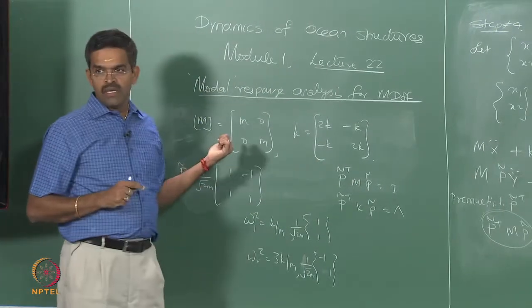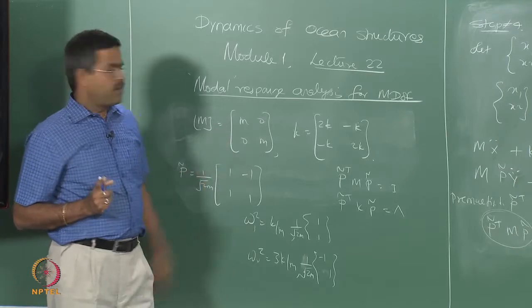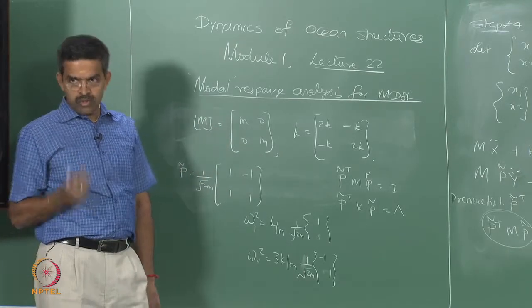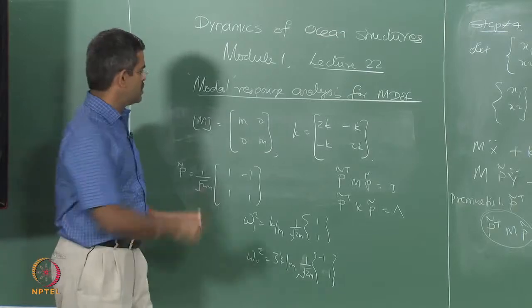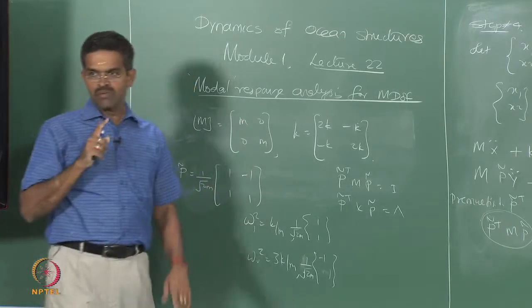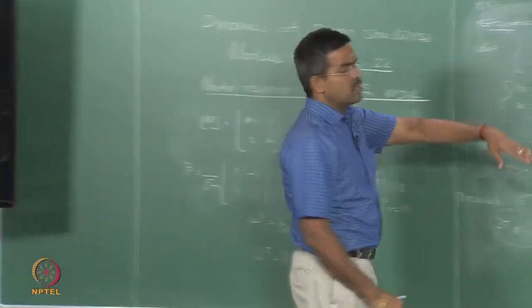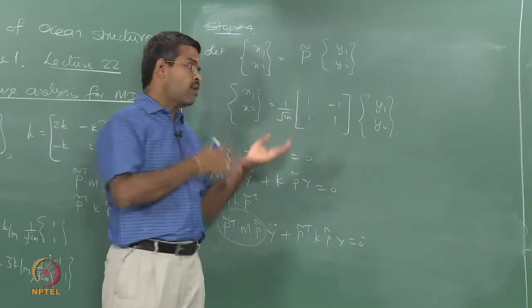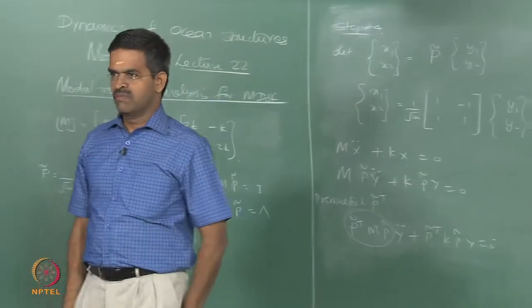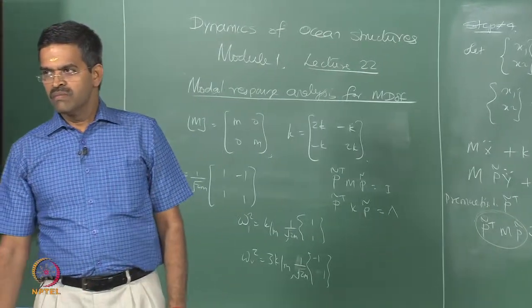and that mass is diagonal, off diagonal terms are 0. Usually it is a practice, but in offshore structures off diagonal terms will not be 0. There are examples I will show you where they are not 0. In that case, equation of motion cannot be decoupled, that is called coupled dynamic analysis. Okay.